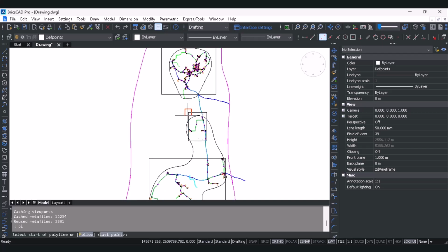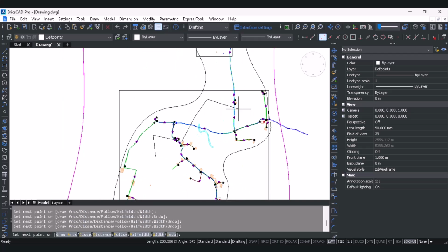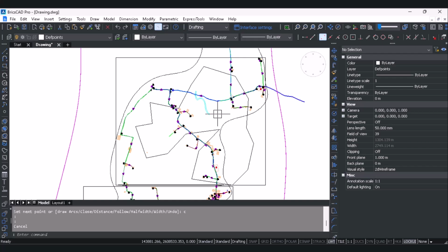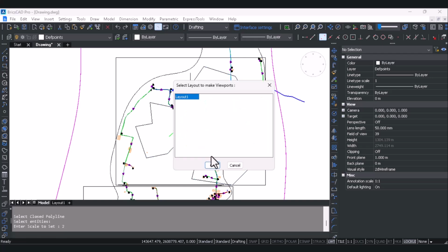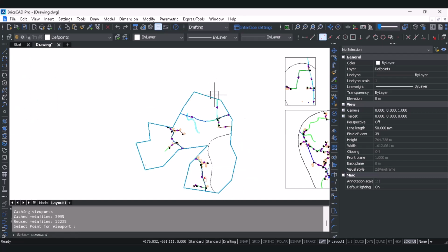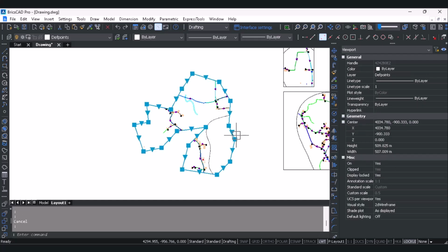Another very beautiful command which I want to show is we can even make a viewport along any irregular polyline. Now let me generate an irregular polyline. You can see it is a highly irregular polyline, and close it. I will run a command called ds underscore poly to viewport. I will select this polyline, scale again 1 in 2, and then it will ask me for a point. You can see the viewport has come along that polyline. Automatically the clipped viewport boundary has come along that polyline.